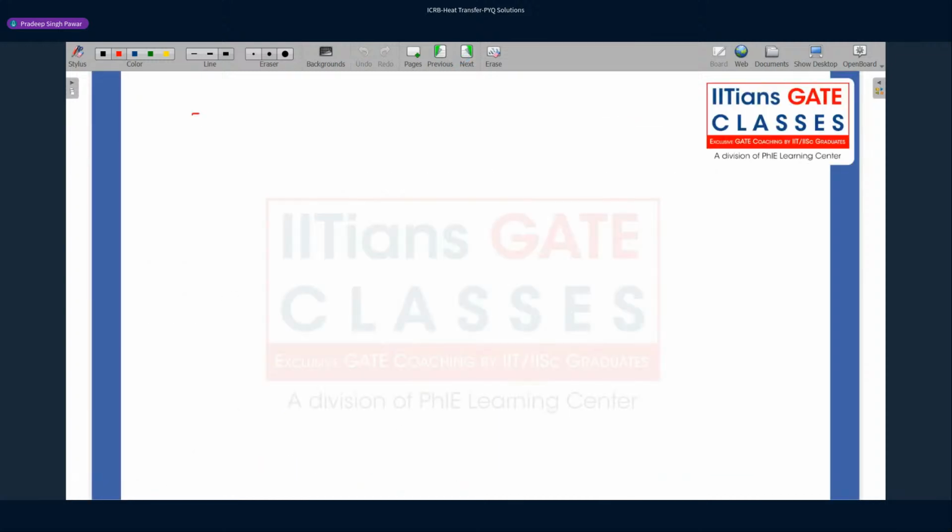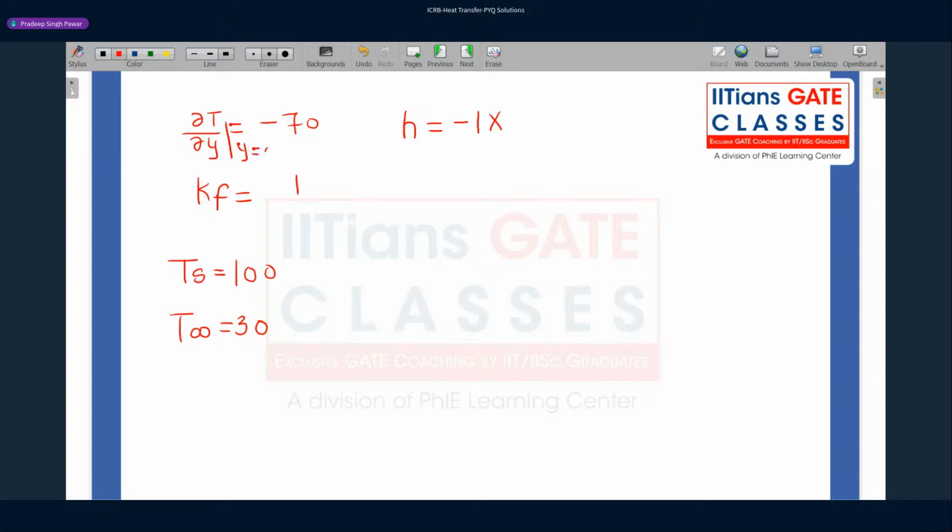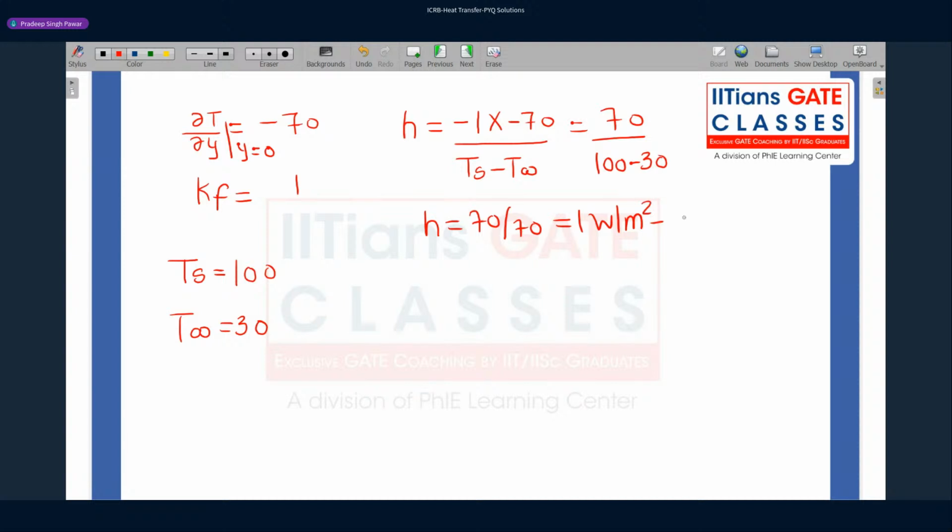Okay, so we got ∂T/∂y as minus 70. Kf is given as 1. Ts is, I think, given as 100. And T infinity is 30. Let's apply. h is minus Kf times ∂T/∂y at y equal to 0, which is minus 70, divided by Ts minus T infinity, which is 100 minus 30, that is 70. So h is 70 by 70, which is 1 watt per meter square Kelvin.